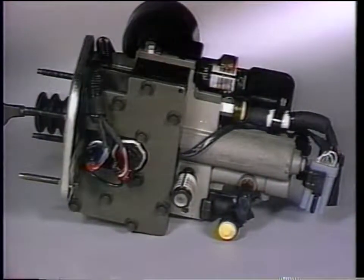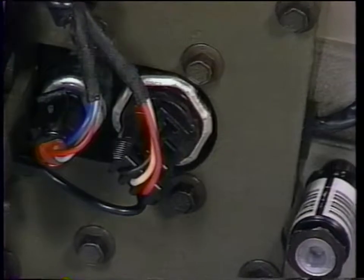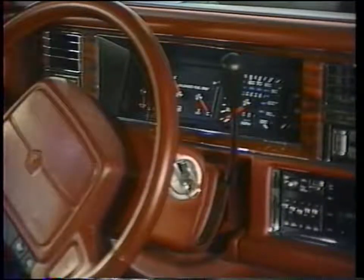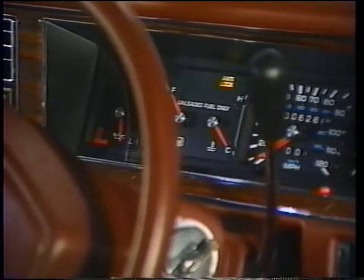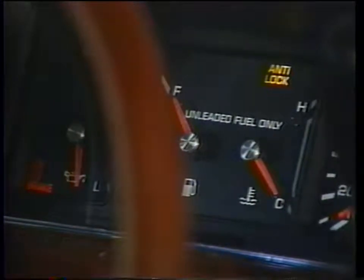Other components on the modulator include a dual-function pressure switch. It's located on the bottom of the modulator. It turns the remote pump motor on and off by grounding the pump motor relay through the starter solenoid. The switch maintains accumulator pressure by turning the pump on when the pressure drops below 1,600 psi and off when pressure reaches 2,000 psi. Like the Jeep system, this switch also warns the controller if accumulator pressure drops below 1,000 psi. When the switch opens, the red brake and yellow ABS warning lights are illuminated, and the ABS system is disabled. A fault code is set if the problem doesn't go away within 2 minutes.